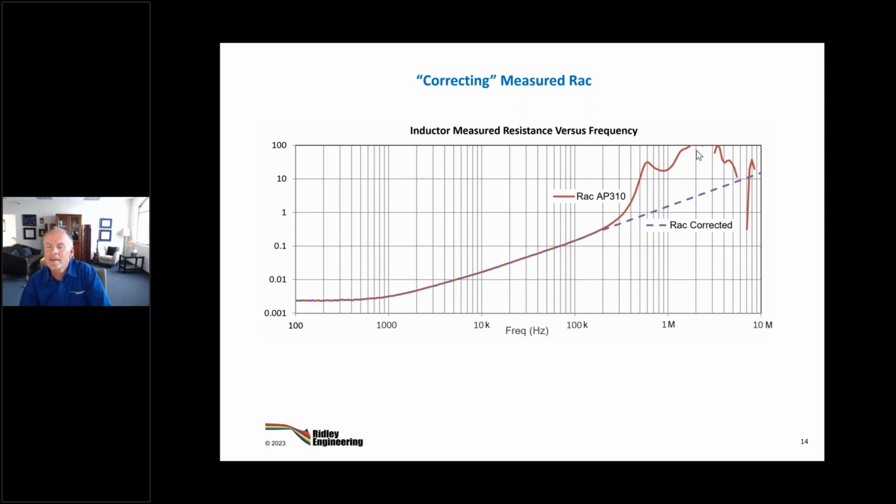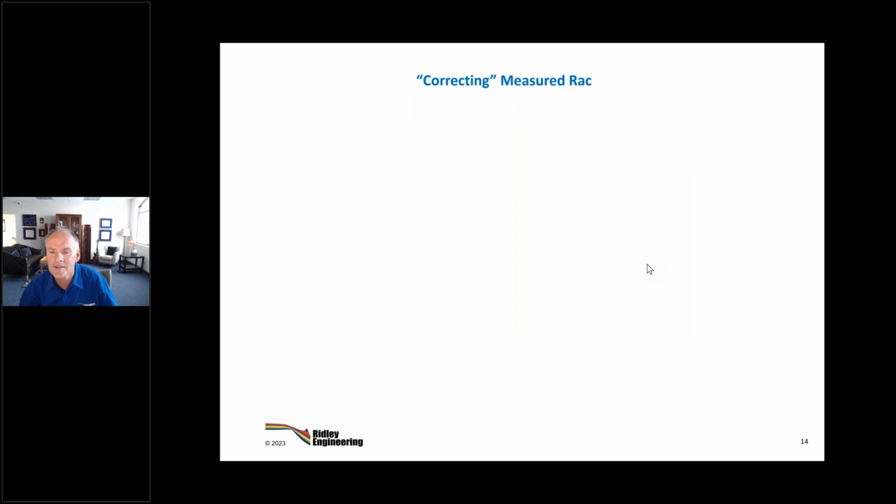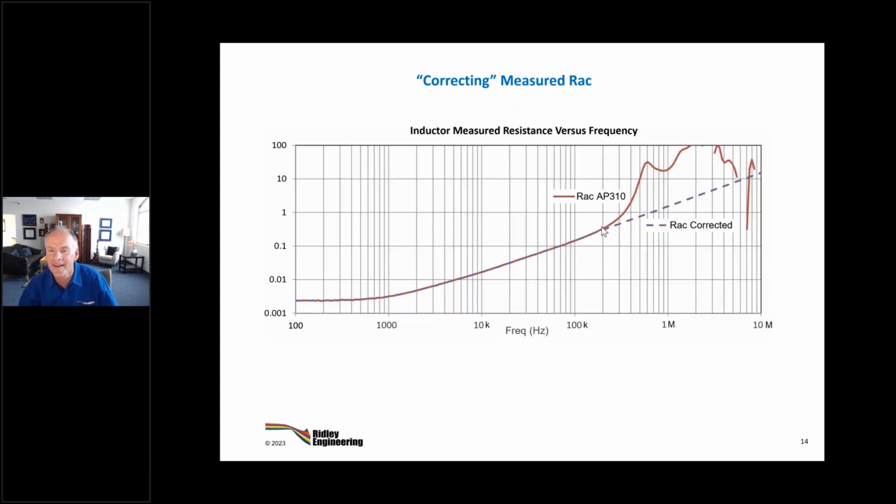and that's why it thrashes around like that. In a lot of the papers, I'm pretty sure in their process they generate curves like this too. So they deliberately wind an inductor to prove proof of concept that has like 100 milliohms resistance, and then it doesn't do this. If you've got an artificially bad inductor to look at, you get much cleaner measurements. So there you go. There's a curve in the wild. I've seen this for 40 years. I've been measuring curves like this. That's why I know, hey, let's correct it.